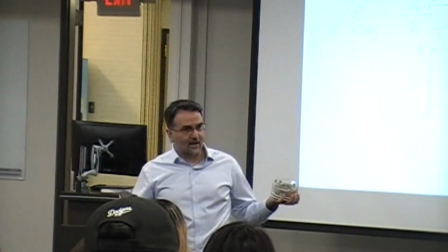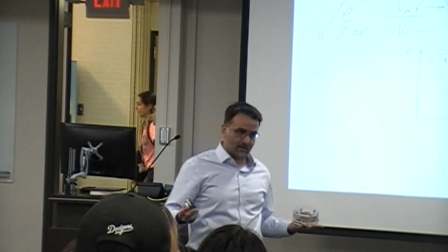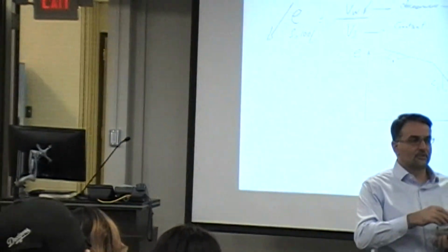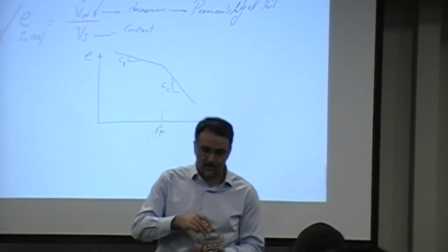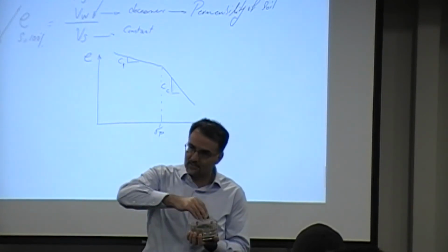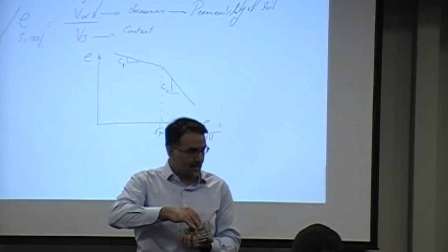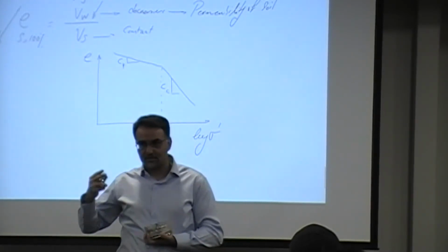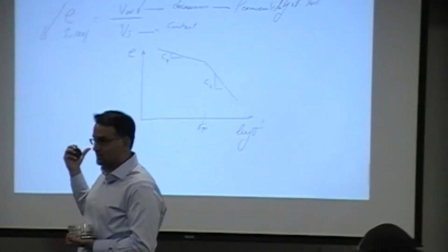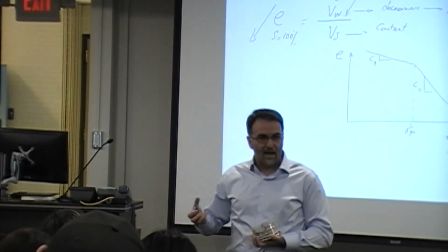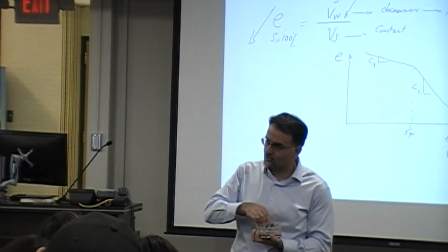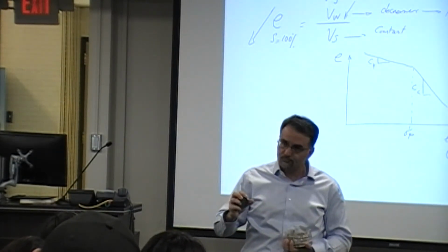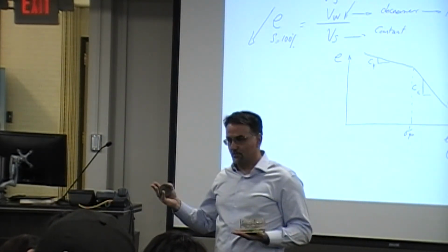Right? So you figure out what the test is about. It's a 10-day test. Right? You basically start with the lowest magnitude of the surcharge, and the surcharge would be the weight that you place at the top of the saturated soil. It's saturated, meaning that volume of air is 0. Volume of water is what is determining the numerator of that void ratio, right? And by increasing the magnitude of the stresses, you see more and more settlement will develop in the system. Make sense? That's basically what the process is.